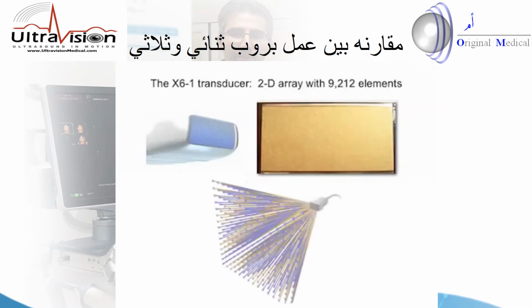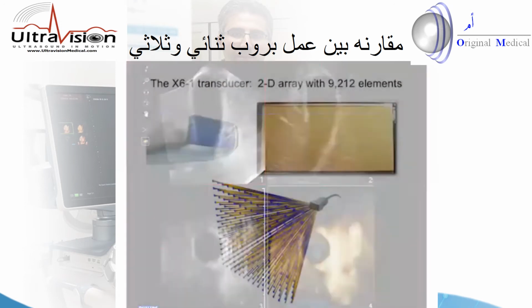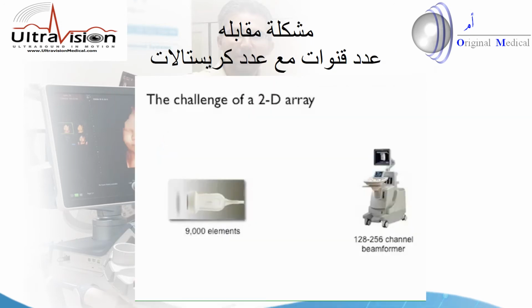Finally, the transducer can be made to sample the entire volume that's available to it, and it's quite a big volume because it's a wide transducer. It can scan up to more than 100 degrees, and these volumes of data can be acquired and processed in real time. It's the transducer that constitutes this advance, because even if you've got a 9,000 element transducer, how are you going to connect it to an ultrasound machine? You can't make a cable with 9,000 wires inside it.